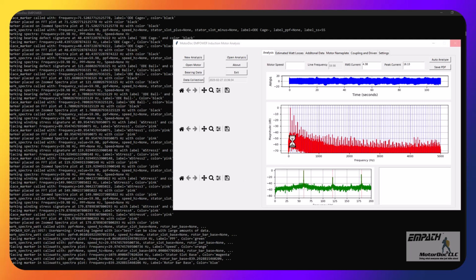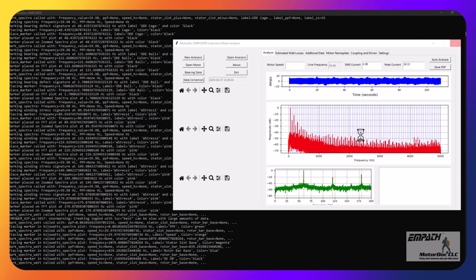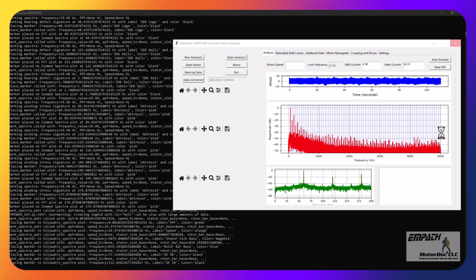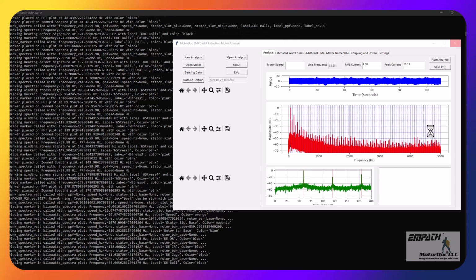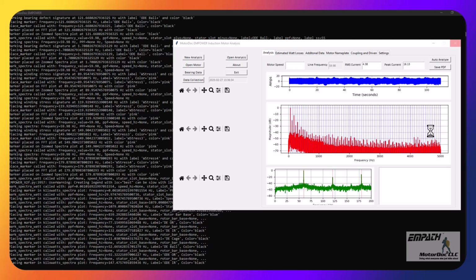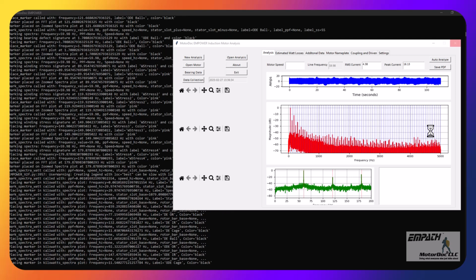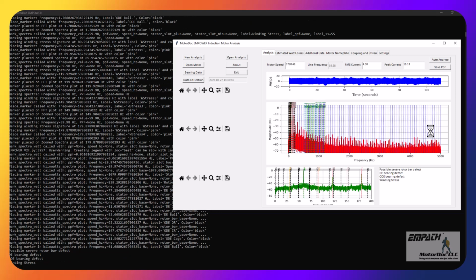Now, this is all the same resolution. As a matter of fact, when we cover some of the other features in here, you'll see even out to 22 kilohertz, we are at 0.008 hertz resolution. That's why we run for 120 seconds. Now, we do lop off the first 10 seconds because sometimes there's some settling in the current clamp, and we want to avoid that settling. And we found that settling can last several seconds. So just rounding it up to 10 usually works.